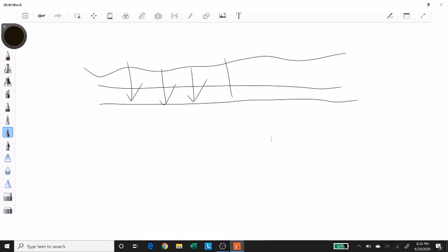And how much to excavate? I can use my level by first, on paper, finding out these excavation heights, and then I can use my instrument to go in the field and actually find out those depths. So it helps not only in control survey, but it also helps in execution as well.